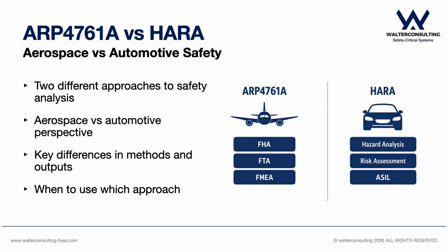Is ARP4761A the same as HARA? At first glance, both seem to do the same thing. They analyze safety risks at system level. But the way they approach this is fundamentally different.